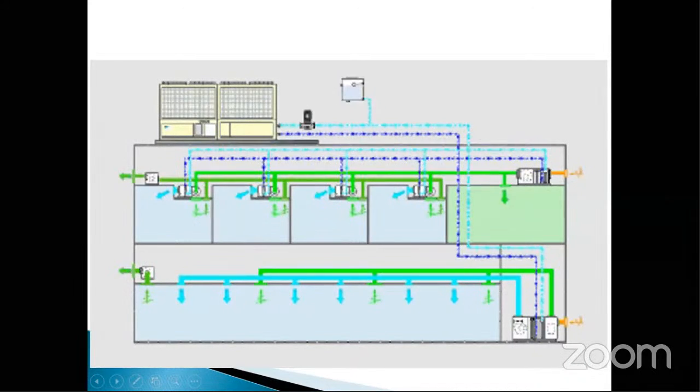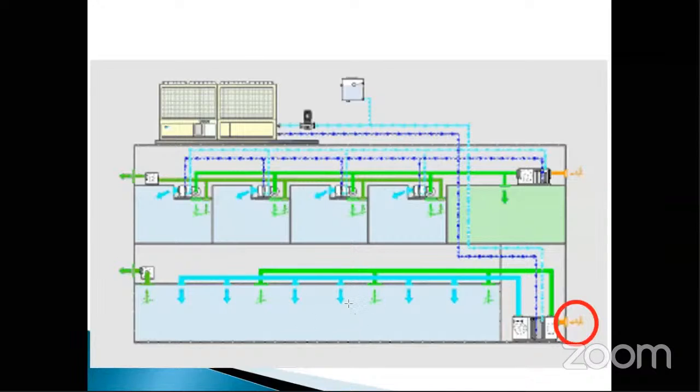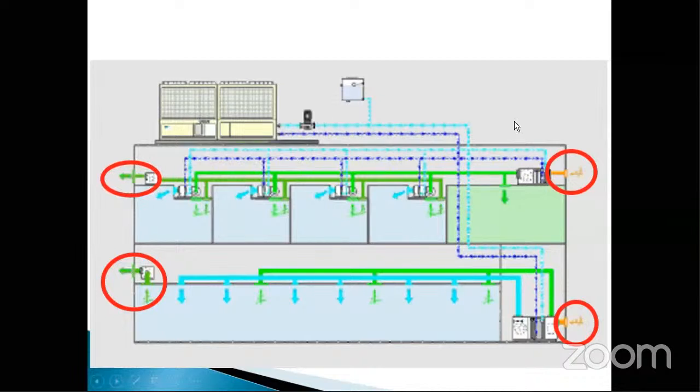You will identify two points here. One is that we are taking outside fresh air, ambient air, because we don't want recirculated air to be in the space, because we inhale oxygen and exhale carbon dioxide. That's the reason fresh air needs to be added. And to maintain neutral pressure, we have to exit this air. Similarly here also you can see we are adding fresh air to the space, and then we are trying to relieve the additional pressure to the ambient.